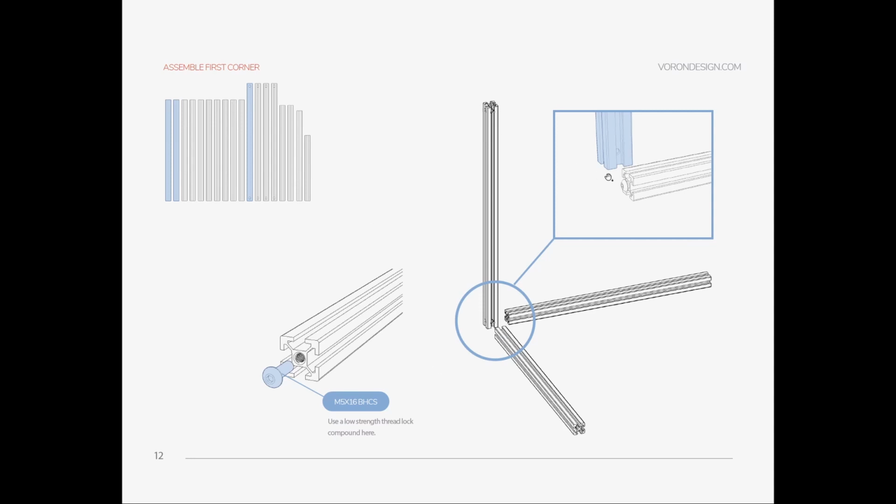And also keep in mind that this cut needs to be flush, because if it is not straight, if it is not a 90-degree cut in here, you will not get a square frame, because this part will sit on this place on the other extrusion. So when you tighten the screw, it will force that. If it is angled, for example, assume that it's a 5-degree angled cut.